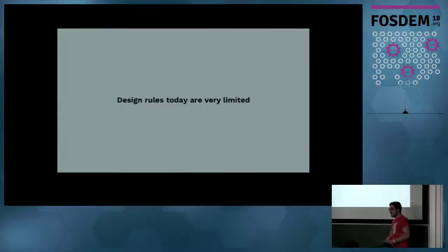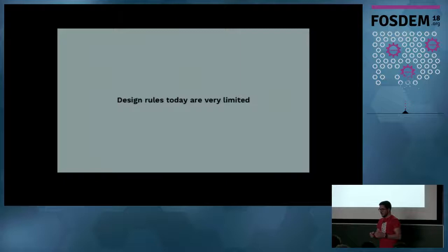It's about making the correct stencil. It's about how to place all the components. It's about how to actually maybe put the PCB into the SMD line. So all of this should be covered in the design rule format.